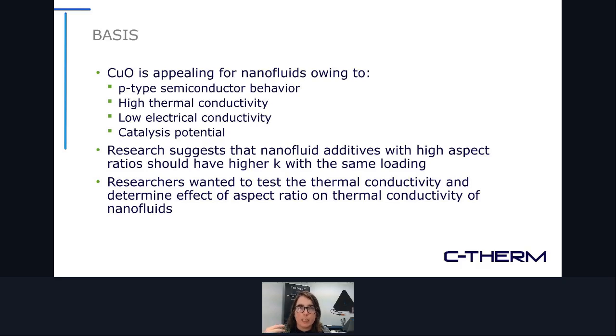a heat transfer fluid, because primarily the main mechanism that you're going to be transferring heat through if you've got a heat transfer fluid is through the convection or the physical motion of the fluid. So if you want to do that, you need to have a fluid that can flow very well. So that's why low viscosity is really a key target right now in nanofluids, because if you have a nanofluid with a very high effective thermal conductivity, but it doesn't want to flow, you're kind of back at square one. It's no more useful than a lower thermal conductivity, more classical heat transfer fluid like a transformer oil or water